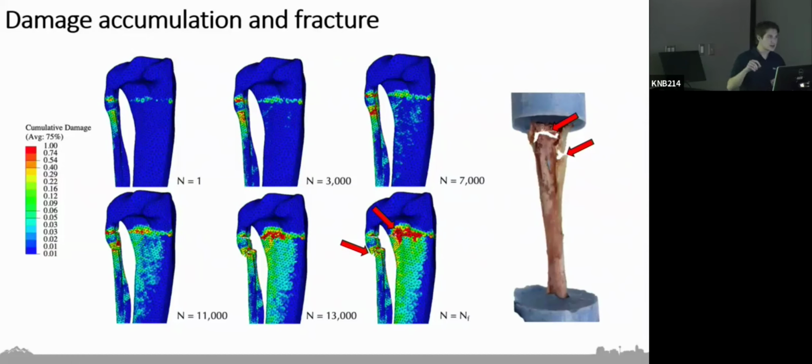So when we change that location to simplex, we can then move around. Ideally, we know the approximate densities that we should expect for bone, and the approximate elastic moduli that we should expect for bone, so we can bound the optimization on those two axes. You might have an elastic modulus between 0 and 20 gigapascals, and a density between 0 and about 3 grams per centimeter cubed. So we wouldn't let the final output go past 3 grams per centimeter cubed in density and 20 gigapascals in elastic modulus.